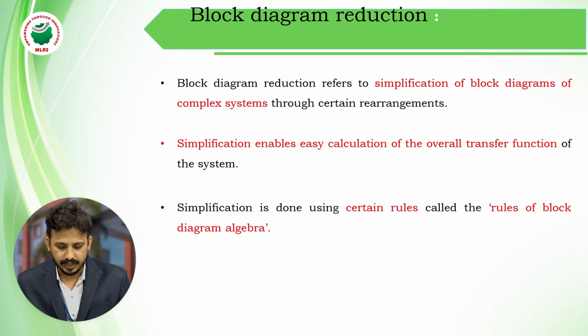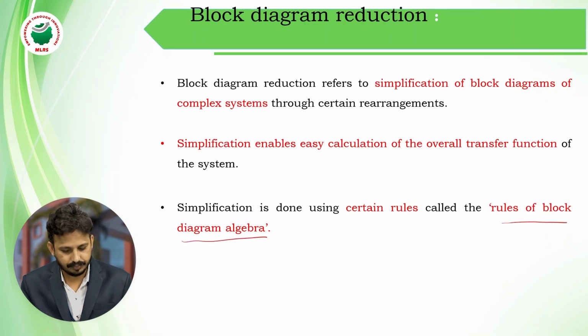Next, block diagram reduction. Block diagram reduction refers to simplification of a block diagram of a complex system through certain rearrangements. The simplification enables calculation of the overall transfer function of a system. The simplification is done using certain rules called the rules of block diagram algebra.